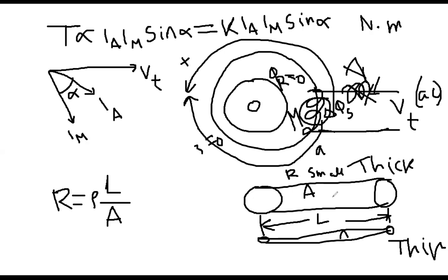If both the auxiliary and main windings were either both thinner with the same length, or both thicker with the same length, there would not be any angle difference. They would have the same phase difference with respect to voltage, the same amount of lagging angle. Do you understand?